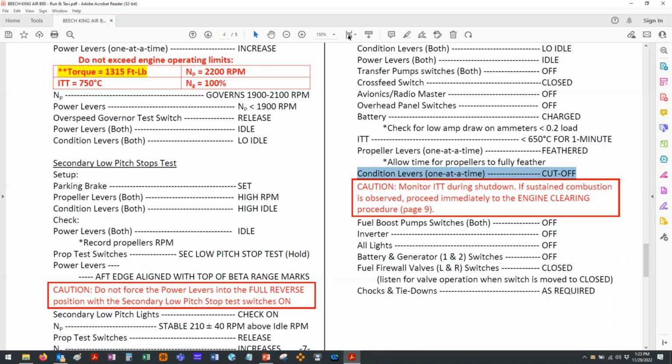So that kind of covers the PT6 and free power turbine turboprops. And next time we'll talk about the TP331, a fixed shaft turboprop. That also will include talking about something called a beta tube. When we talk about beta tubes, those aren't unique, however, to a fixed shaft turboprop. There are free power turboprop aircraft that use the beta tube. It's essentially an internal pitch change and feedback mechanism rather than the external one that's used on some aircraft.